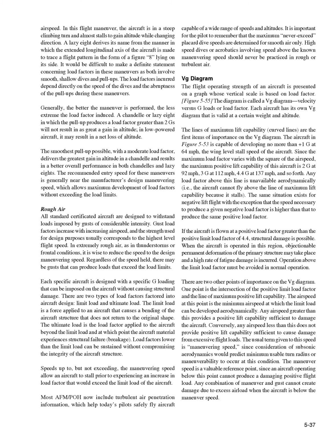The maneuver speed is a valuable reference point, since an aircraft operating below this point cannot produce a damaging positive flight load. Any combination of maneuver and gust cannot create damage due to excess air load when the aircraft is below the maneuver speed.